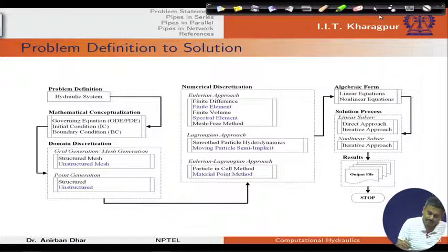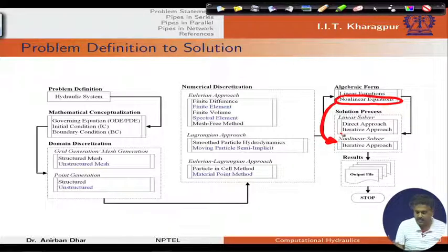Now, in this case also we will see that we need to solve some nonlinear equations. To solve nonlinear equations we will require a nonlinear solver or our usual Newton-Raphson method, but in Hardy-Cross it is a modified Newton-Raphson kind of method.